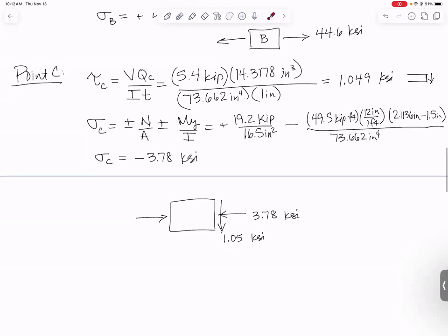That would not be an equilibrium. So this downward arrow on that side needs to have an upward arrow on the opposite. And then can you see that this little square would start rotating because these two are unbalanced as a moment? So we also need to draw another pair of arrows like that so that the heads point toward each other. What we used our original diagram for was to figure out the direction of the shear stress on the side that matches up with our cut face. Once you start with that, you just add arrows that are head to head and tail to tail. And that is what the stress state would look like at point C.